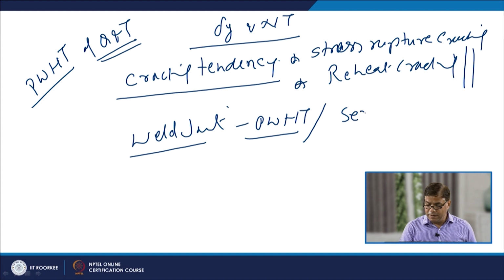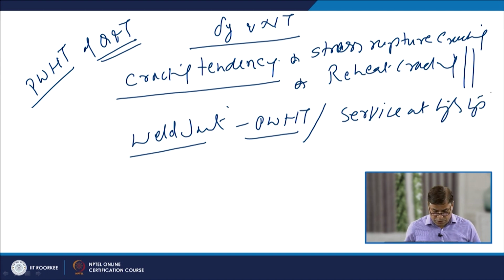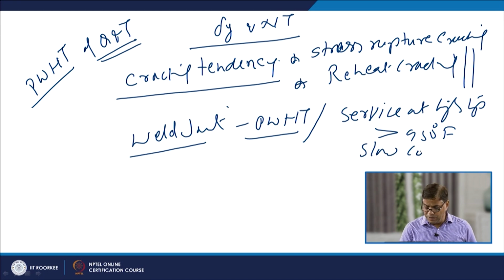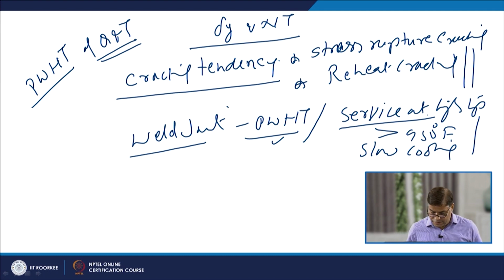to high temperature service, at a temperature greater than 950 degree Fahrenheit, followed by slow cooling. So, either after the welding, or when exposure is being given for stress relieving during the post weld heat treatment, or the weld joint is given exposure at a high temperature during the service followed by slow cooling.